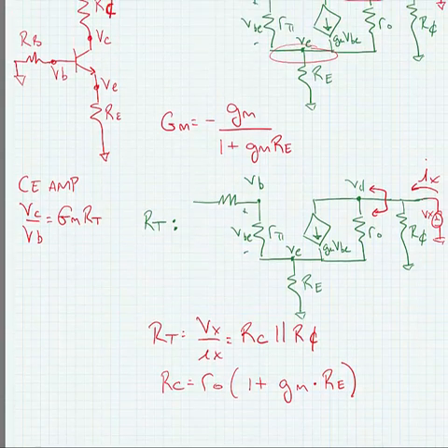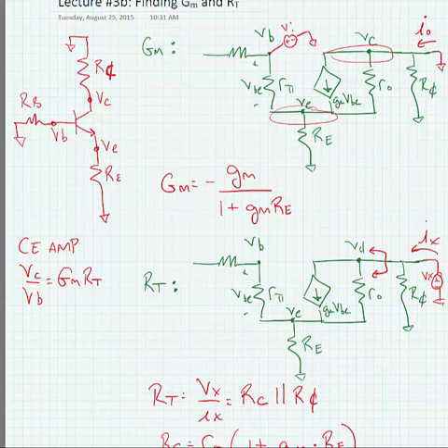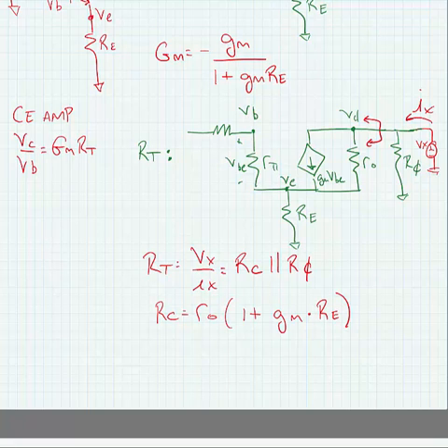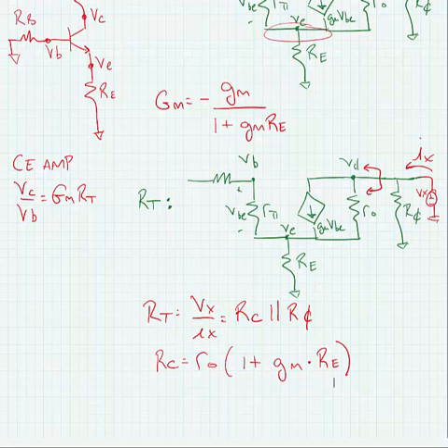So what we really see is going on with a voltage amplifier is that the transistor first turns an input voltage into an output current. That output current flows through a total output resistance that converts the current back to a voltage. Now we'll, in the next set of slides, write out a generalized expression for each type of amplifier that exists: common emitter, common base, common collector for the BJT cases, and common source, common gate, and common drain for the MOSFET cases.